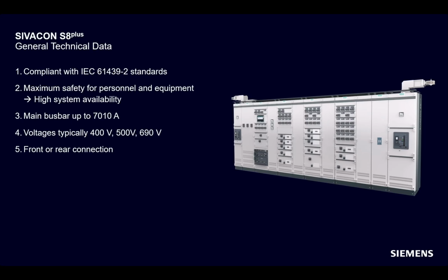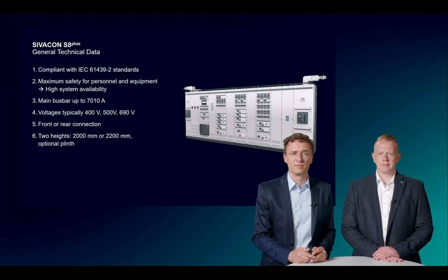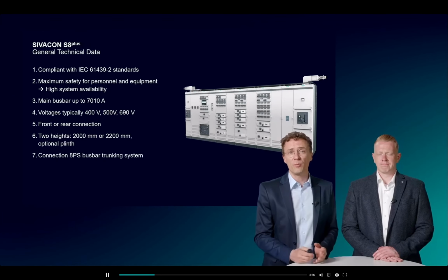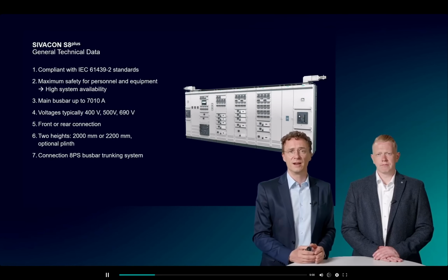Because we have to measure voltage on 400 kV systems, we also offer an easy way of connecting our SIVACON 8PS busbar trunking systems and our insulation sections for 400 kV transformers. You see a current transformer for switchboards, 400 kV, and tap-off units as an alternative to using cable connections. You also see a voltage transformer design where the voltage is connected somewhere down there. This type of connection is also verified. Our uniform operating concept helps the operator to prevent operational errors.